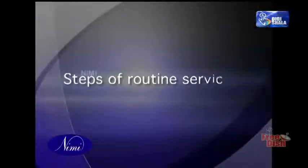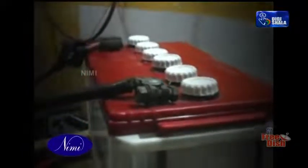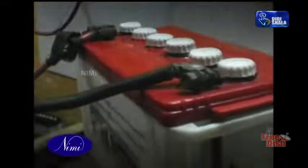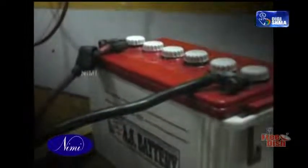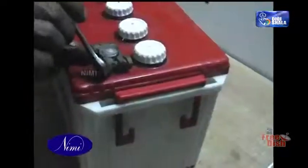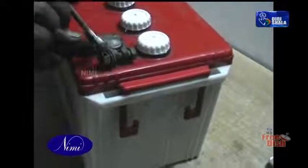Steps of routine servicing of a battery. Make a visual inspection for defective cables, loose connections, corrosion, cracked cases or covers, loose hold downs and deformed or loose terminal posts. All connections should be tightened and replaced if necessary to ensure proper connection.